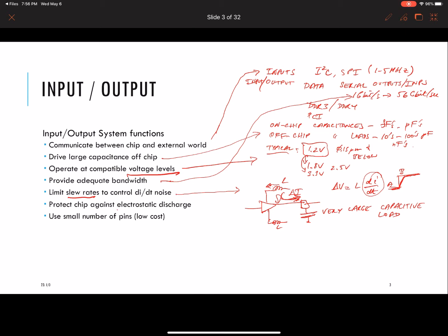Then there are environmental issues out there, like electrostatic discharge. We'll talk about that a little bit. We're all familiar with it. It's sort of what you pick up walking across a carpet, but as I'm sure you know, it could be pretty destructive to microelectronics. You could build up tens of thousands of volts, certainly thousands of volts. Very little current, mind you, but thousands of volts. And if you zap your circuit without adequate protection, you can destroy it.